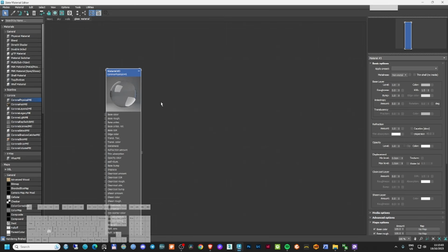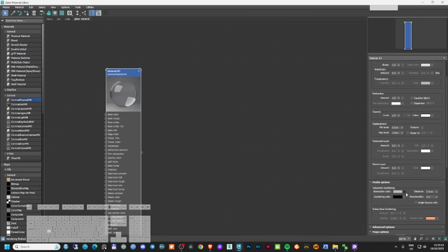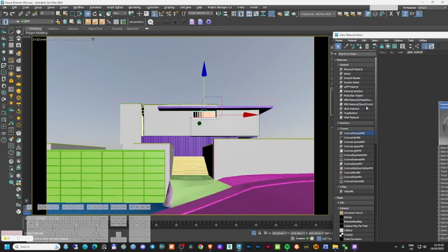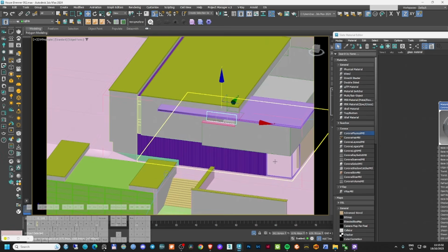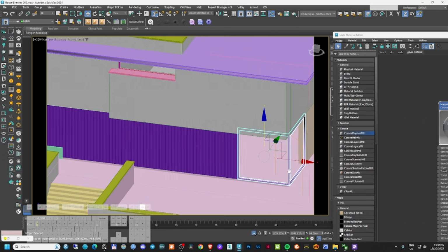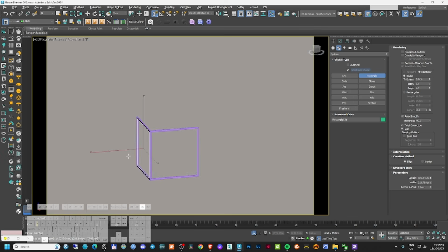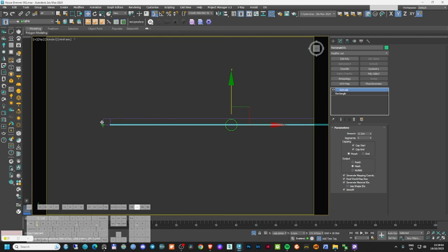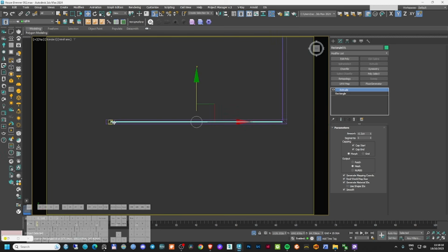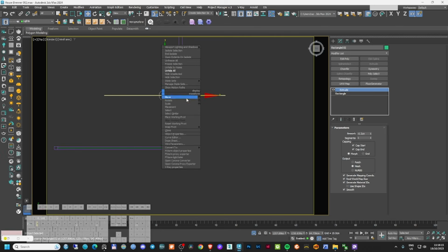If you want to add a tinted color, that's quite easy to add. Go to media option and use an absorption color, and here you can say how long is the absorption inside the material. I'm not gonna do that today because I don't think it's needed, and I will just apply my glass to this one. And also I think here I didn't create the glass sheet. Let me do that right now. Smooth. Middle point, just move this here, make a copy, rotate all of this.